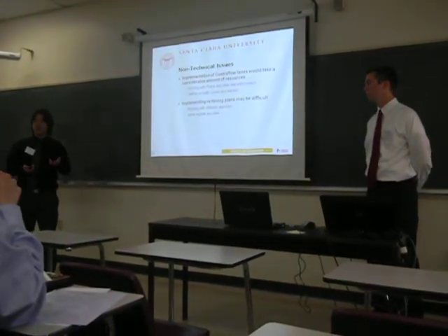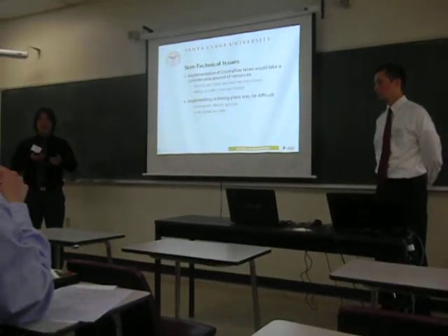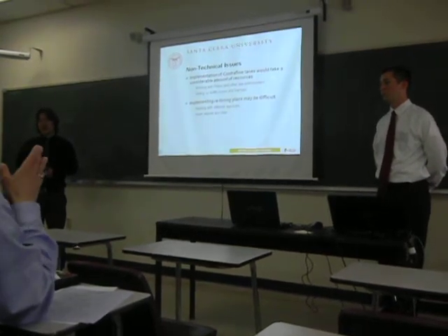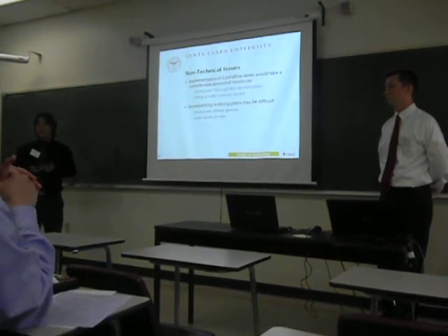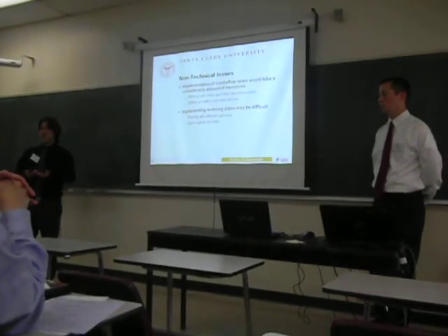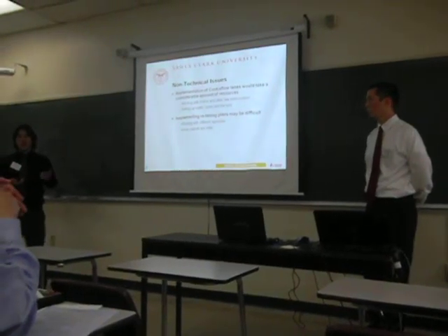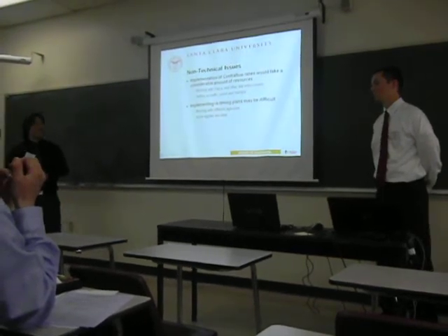And implementing these signal retiming plans would also pose problems sometimes because, as Jake said earlier, a lot of these timing plans are under different jurisdictions, so we'd have to coordinate with the city of Santa Clara, the city of San Jose, etc. And some of these signals are also older, so while a lot of these new signals may be able to be retimed electronically from, say, an office, some of these older signals will actually require a traffic engineer to go out into the field and manually change these timing plans.